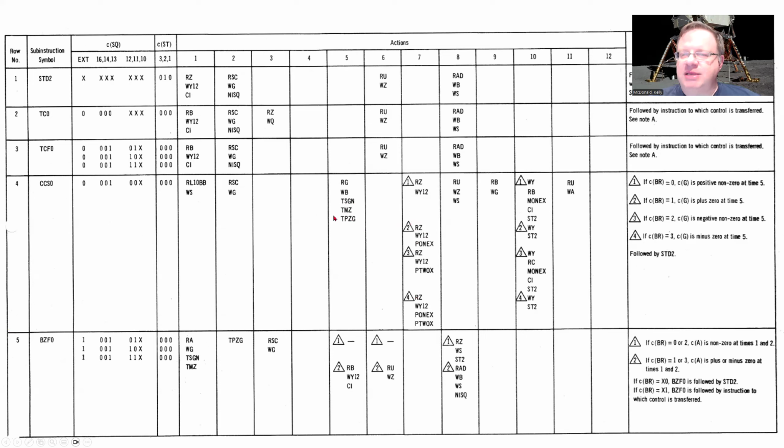And so this is basically how we can get a lot of functionality with just 2 branch register bits. On a more modern processor, you might have a whole bunch of different flags, like is the contents of the accumulator 0? Is the contents of the accumulator negative? And then, based on that, you can perform branching. In this case, the AGC just uses those 2 bits, and then they can be set depending on different tests that the computer instructs to run at previous sequences.